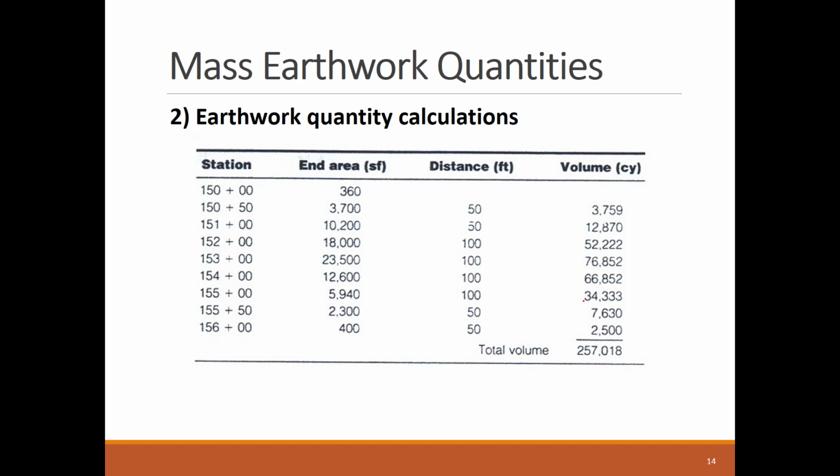Please notice that all end areas are for excavation cut, not backfill or fill, because all the end areas are positive. So the area calculations are sign sensitive.